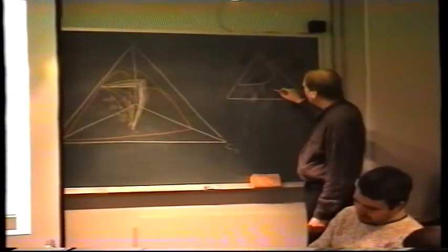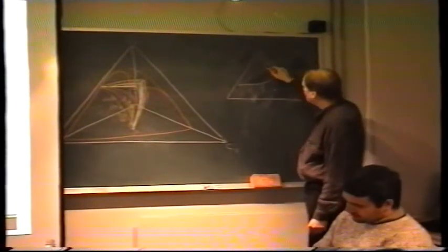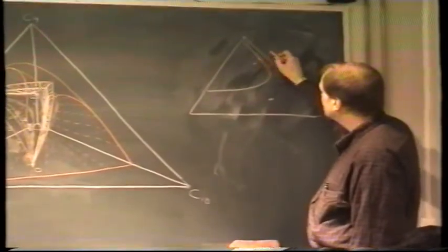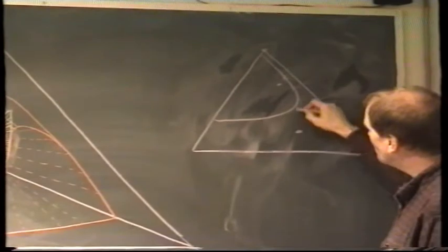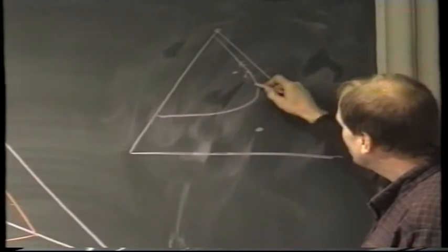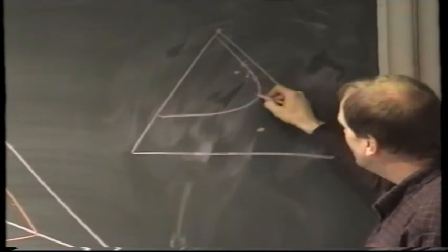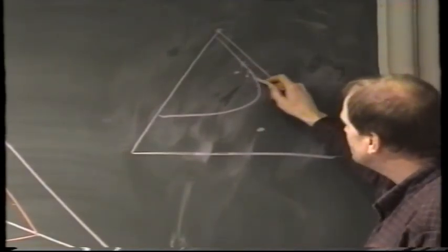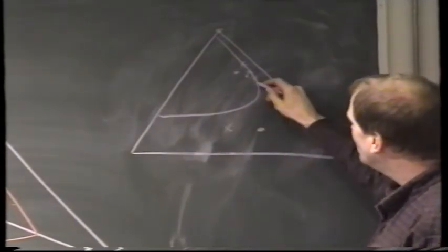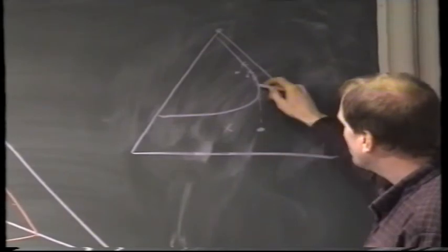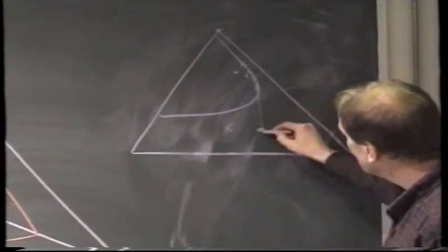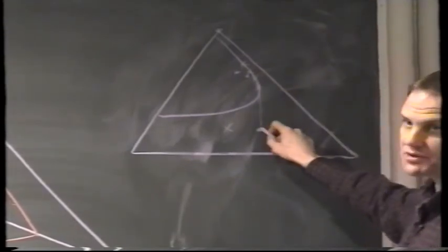You inject some oil into the gas, let it equilibrate, you get a new gas here, and you inject some more of that oil into this gas, let it equilibrate, and inject this into the new gas, and so forth, until you either get stuck on a tie line for this gas, for this oil, or until you reach a condition of line of sight miscibility for this oil.